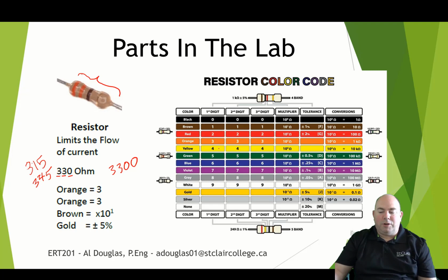Now, if you know what this chart is, maybe you just know things off by heart. The other thing is you might know that we always use orange, orange, brown resistors. This will be a common practice when we're actually using the kits, is that you want to pull up an orange, orange resistor every time you use an LED. That's what we use with our LEDs. Okay, so that is resistors. The direction of them doesn't matter. If you put them in backwards, it doesn't matter.